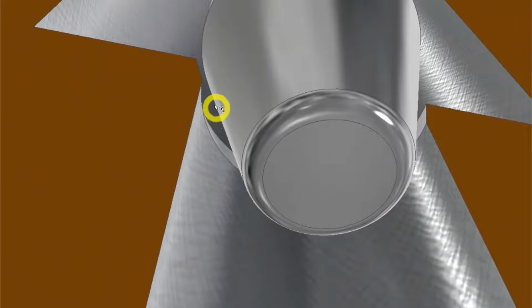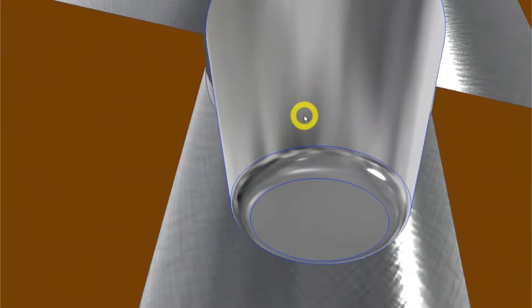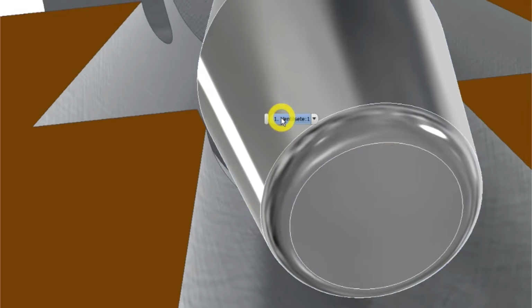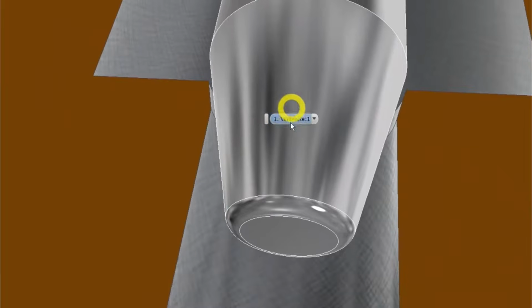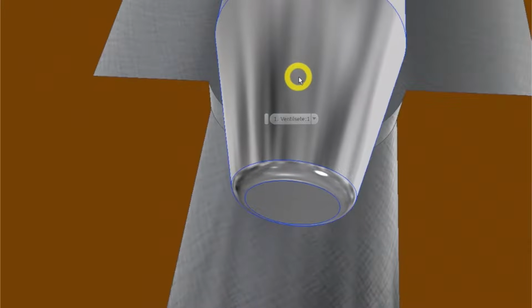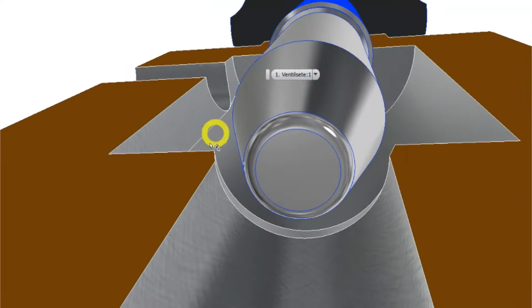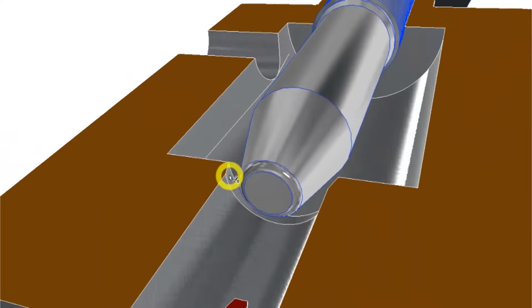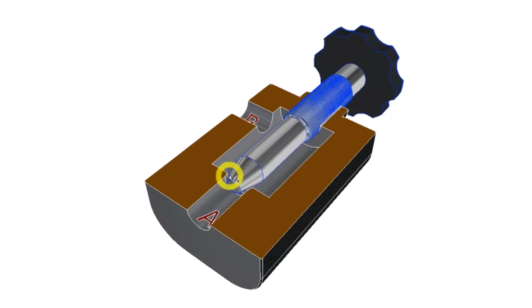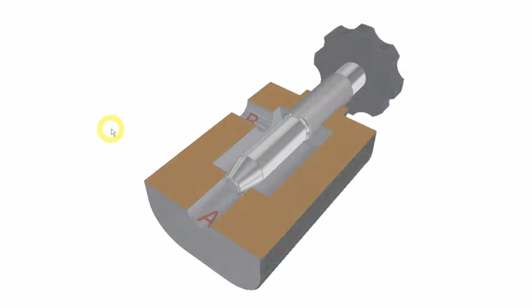If you turn the valve wheel and adjust the plunger downwards, you will obtain an even narrower opening and the volume flow will be further reduced. If you adjust the plunger upwards, the opening will increase and it will be easier for the pump to press liquid through the valve, and the flow and speed of the component behind will increase. It is a very simple principle, similar to the way your kitchen faucet works. A faucet is a combination of an on-off valve and a choke valve.